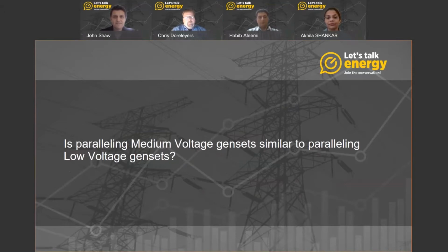In many cases, for large low voltage generators, the fault current is often high. On typical switchgear, the maximum kiloampere or kA rating for switchgear of any voltage is typically 100 kA.